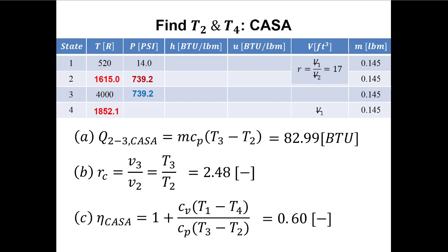The next thing we need to know is, is the system open or closed? So we model all of these processes as closed system processes, even though we know that's not strictly true. Then we ask, is the working fluid air, or water, or something that looks like it? In this case, our working fluid is an ideal gas, air. And in this case, we assumed constant specific heat. But for the Otto cycle, I showed you also how to do problems with variable specific heat.